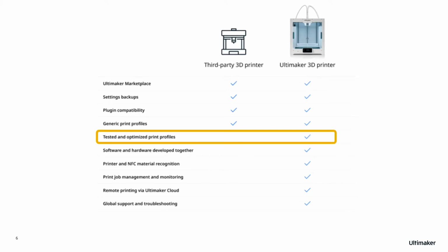Ultimaker Cura gives you access to over 400 parameters across 13 sections via the custom print settings button. With this, you have almost unlimited control to adjust and improve your print quality for any 3D printer. Of course, changing and testing even a few of these settings takes time. For busy engineers and designers, this is where pre-configured material profiles become a big time-saving feature in Ultimaker Cura.